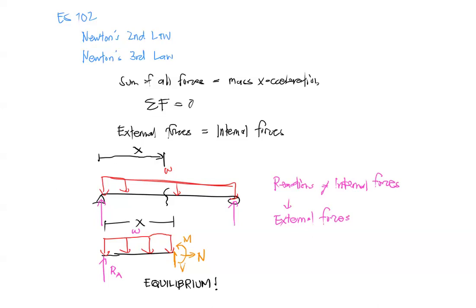So, given that it's supposed to be in equilibrium, we can do again the analysis knowing that the section portion of the beam is at some distance, has some length x. So, if chinek natin yung equilibrium, so summing all forces along x to be equal to 0, since wala kang axial force na nag-act upon dun sa beam mo, what you'll determine is yung normal force mo, and ititreat natin to as a function of x is equal to 0.